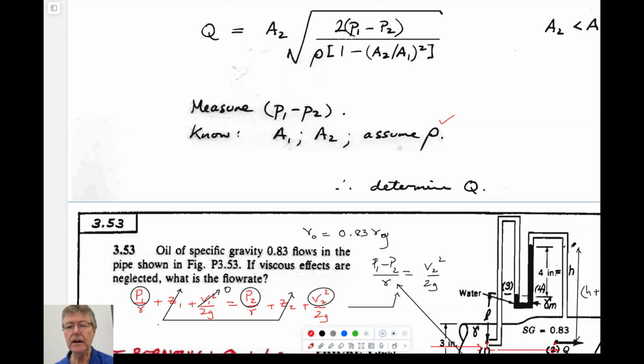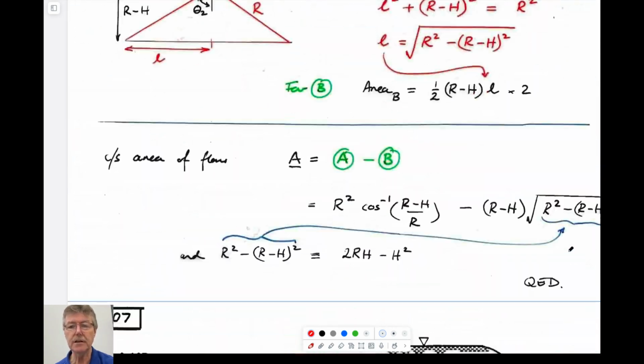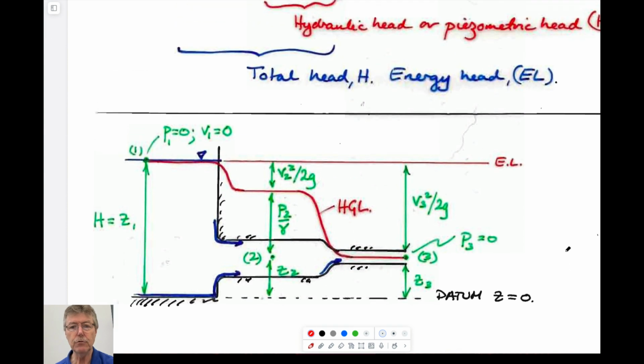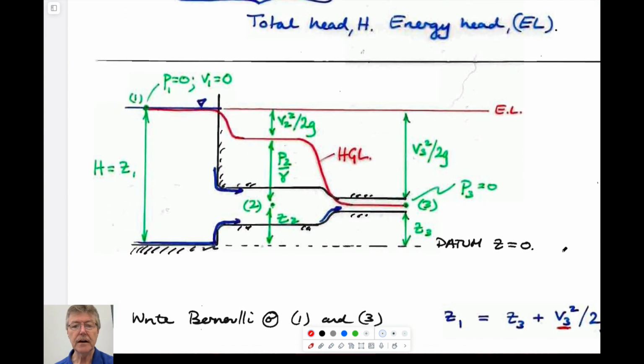So anyway, that's a useful way to think about these things. The other way to think about it is in terms of this other diagram that you have here. Don't want to give you whiplash. Exactly the same expression that we've done before. I guess I was wrong. Yeah, that's right. The hydraulic grade line is just the one that goes on top of the elevation, the pressure. But we can draw this for a more complicated geometry. We haven't put in the pump amounts. This is our energy grade line. This is what we've called our EGL, or energy line.